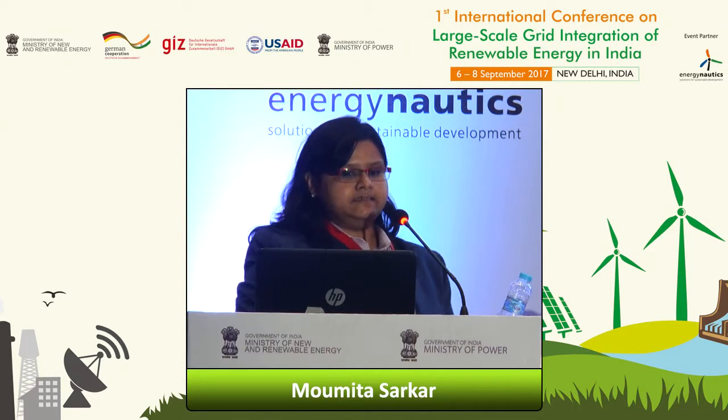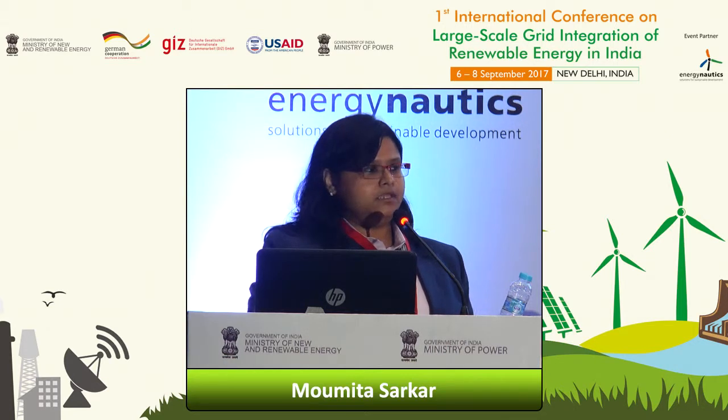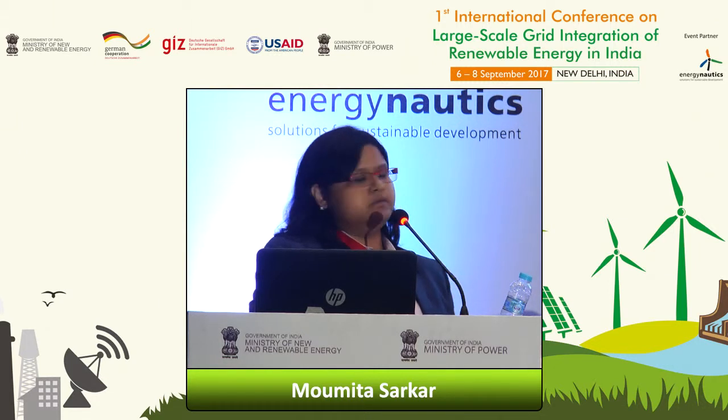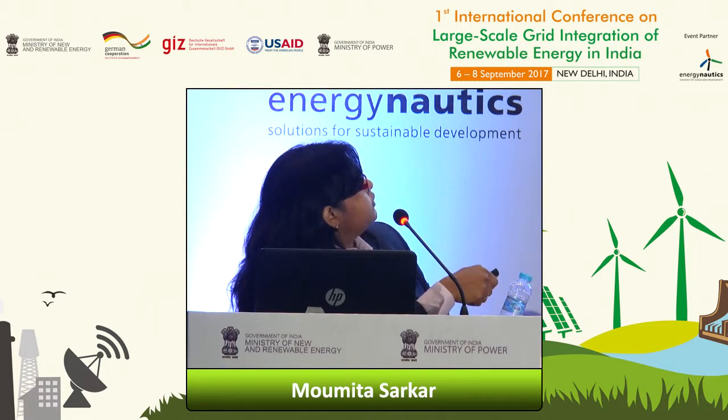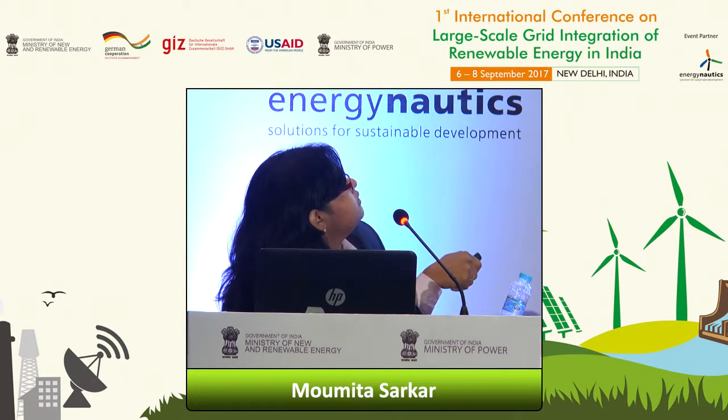Next, the steady-state analysis. What we did is some power flow, and firstly we operated the wind power plant in V control mode with the reference voltage as 1.04 pu. In a pre-fault scenario, the voltage at the observed bus, that is bus 111, was 0.95 pu. But when the fault happened and the line got disconnected, the voltage at this bus falls to 0.92 pu. And the reactive power output from the plant was 0.22 pu.